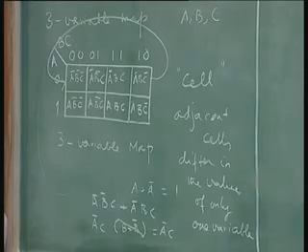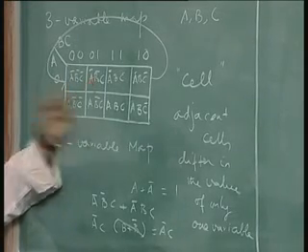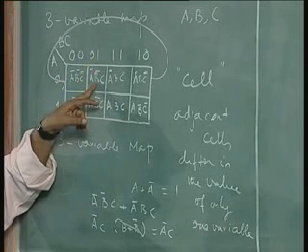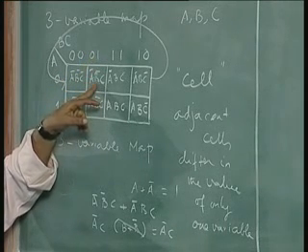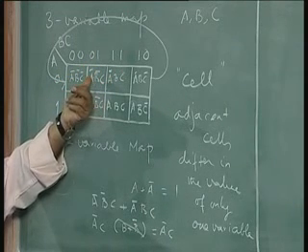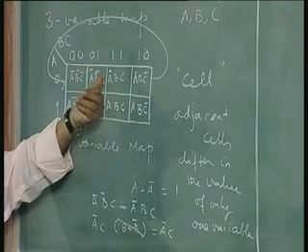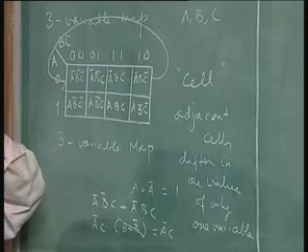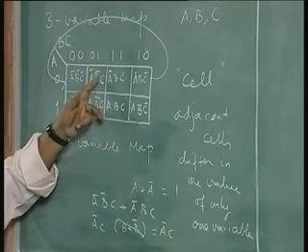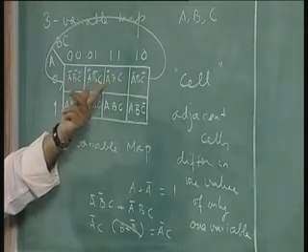So what does it mean now? If I have a value whose output is 1 or true for this case, and for this case, that means the truth table will have a 1 in this cell as well as in this cell. When I have 1 and 1 in two adjacent cells of the truth table, I can knock off the variable which is different between these two cells and have a simplified expression. That is what we did.